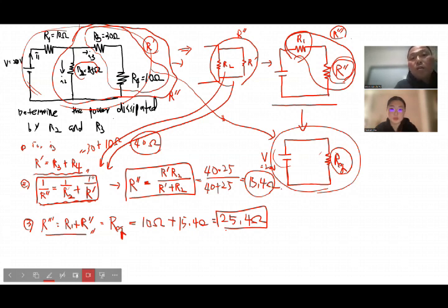So now the next step is to set up the loop. You can set up any direction of a loop along this current path, but it's always easier to follow the mainstream of the current path. So now, as you can see, I1 goes along the I1 direction, right? So clockwise. You can choose the direction of loop 1 to be the same direction as current I1. So for loop 1,